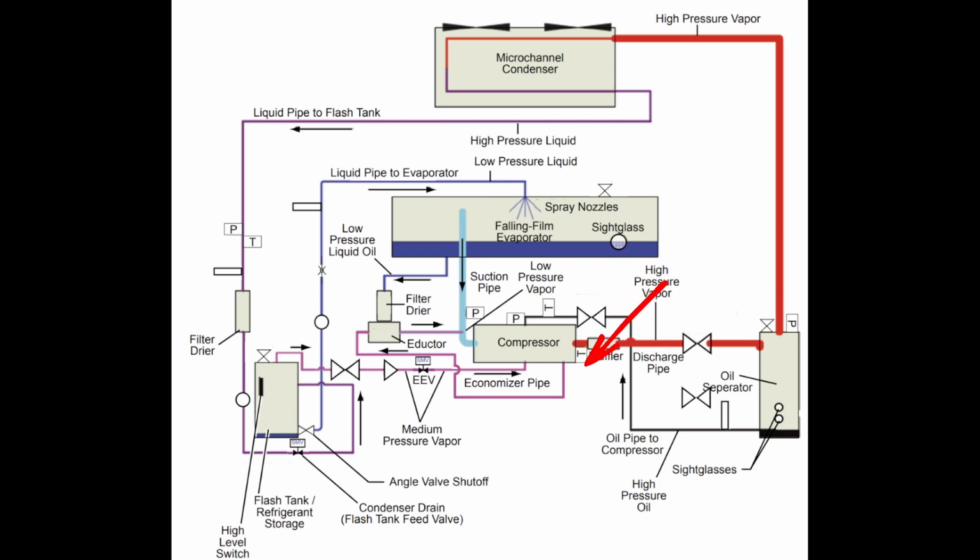side. Now I do want to make one clarification with this schematic. This particular schematic is referencing the early versions of the YVAA, where the eductor hot gas line got tied in at the compressor discharge. They stopped doing this because, one, this refrigerant here is already very oil latent, because it hadn't even made it to the oil separator yet. But also the vibration of this line right here at the compressor, they had a lot of issues with it blowing out and fracturing or cracking, dumping the charge.